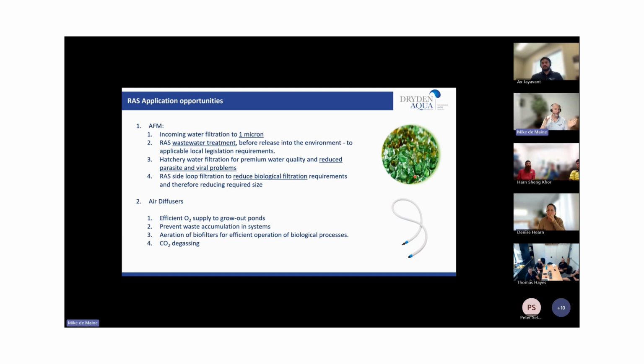So you're using drum filters to remove particles down to 30 microns, and quite often protein skimmers to remove the particles from 5 microns and lower. But there's that gap between 30 microns and 5 microns that is not being dealt with. Those particles are ending up on your biological filters. Your biological filters are then becoming filters first before they become biologically active, right?